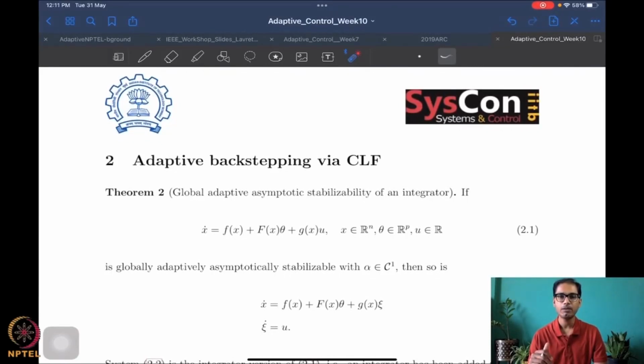Because what does backstepping mean? It means that I add some integrator layers and I can still apply the same method. The adaptive integrator backstepping essentially meant that I can design a controller for the first stage, but then if there's an integrator layer, I can just move this controller to the second stage using a smart construction of a Lyapunov function. Here also we do something similar, right?